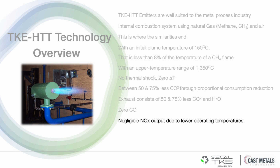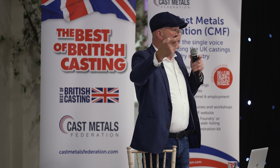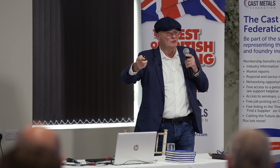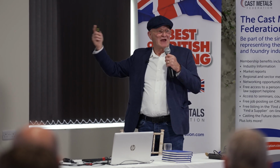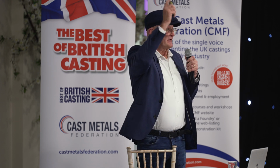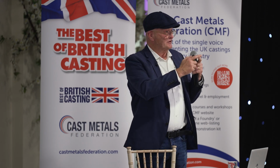Now, if your operating temperature doesn't need to go high, give an example, a ladle heater, you normally put maybe 1,200 degrees into it. I know the largest steel company in the country puts 1,450 in to try and get the refractory to retain the heat. We could do the same at about 1,150. So we're well below the thermal NOx threshold where it goes stratospheric. So it's very, very friendly in that respect. And we're also able to swap out at a ratio of 20:1, removing 20 burners and putting a single emitter in and still maintaining the uniformity.